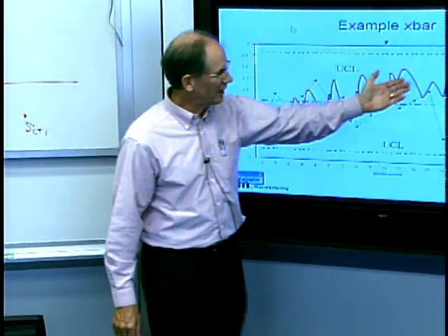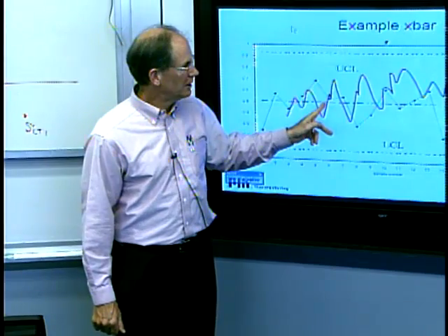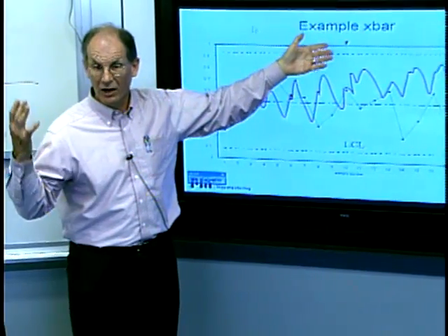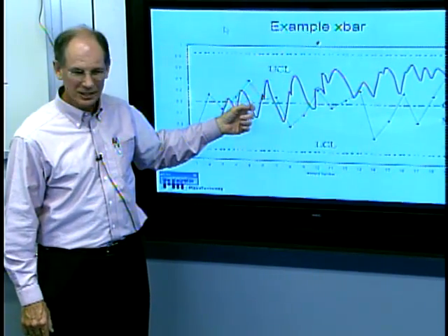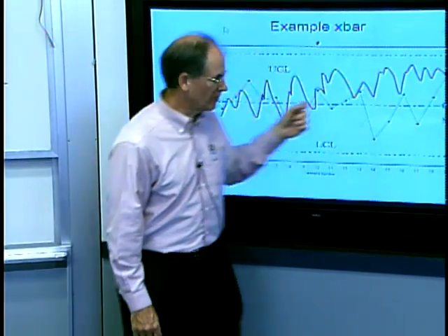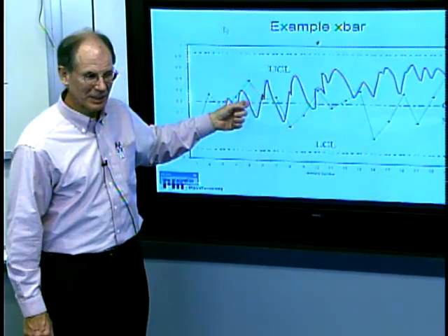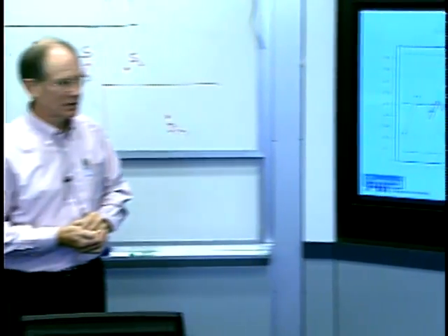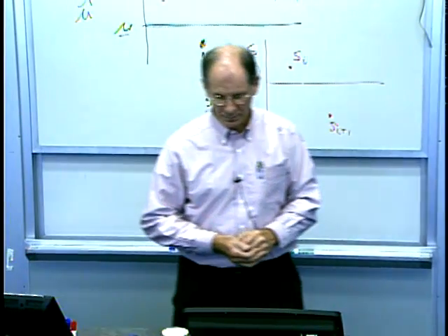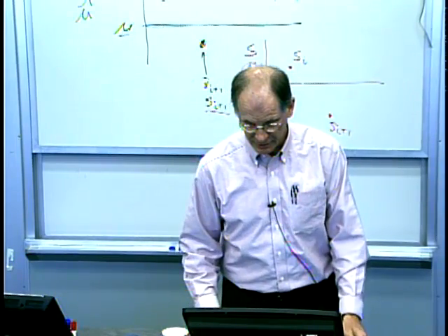Yeah, look, it's trending up like crazy. When did that trend begin? Like maybe here? Now, if all I do is have an alarm when I cross over this upper limit, can you see that something's been wrong for a long time? And this could be hours. It could be milliseconds, but it could be hours. Something's been going wrong for a long time. It would be nice to have something a little bit more subtle than just simply waiting for that one random, potentially purely random event. Although I'll talk about that in just a second.